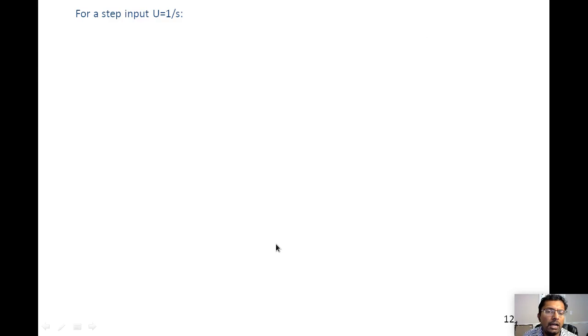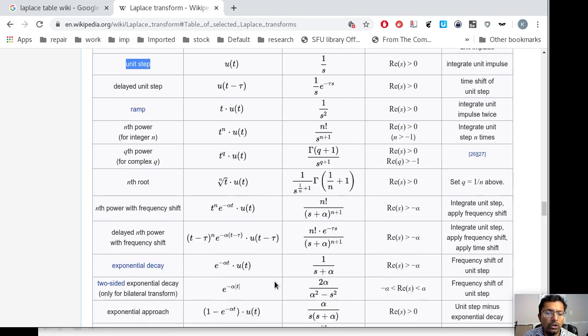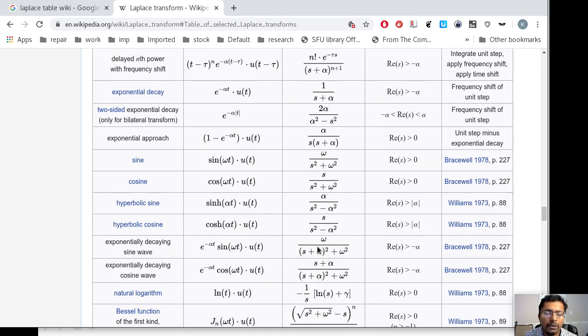Once you have that, we're going to calculate the response of the system. It basically becomes just G times 1 over s. If we go back, we have two options here. We can multiply the denominator out, where I'll get cubic terms, and then try to figure out what the inverse Laplace is going to be. But if you go to the Laplace table, it only has terms up to s squared. So this would be a problem. What we need to do is go the other way, and find some way of transforming this equation into a combination of lower powers of s in the denominator.